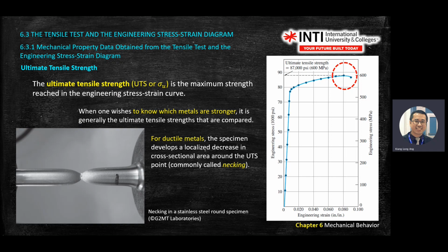By looking at the behavior of the sample, especially aluminum, when you pull, you see a reduction of diameter, we call it cone behavior, where it becomes a cone. This normally happens to ductile material. This is called necking. Necking normally happens near the UTS. It is very obvious in an aluminum sample. Other samples might not show this behavior unless you pull very, very slowly.